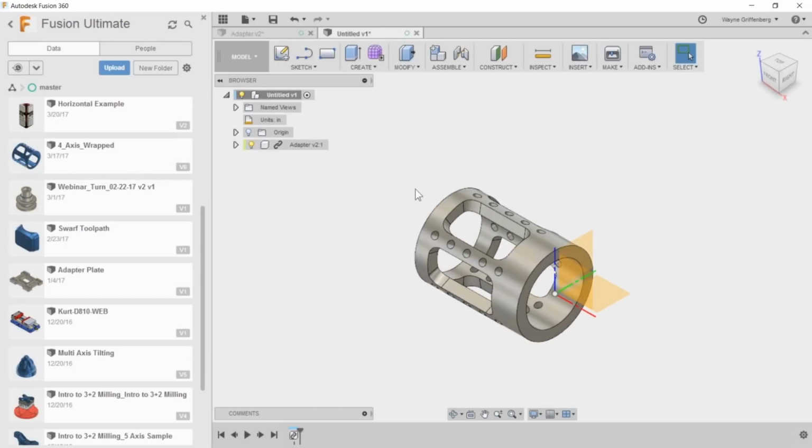But it's good to do. It's a good way to mimic what's going on really in your machine and save that table. Like if I brought in the vise and that's what's on my machine, save that as a template. Because then you can put your toolpath in that template. You can just drag your part in. You're already oriented. You already have your G54 set up. You might even have some tools in that template. You just apply your toolpath and you're good to go.